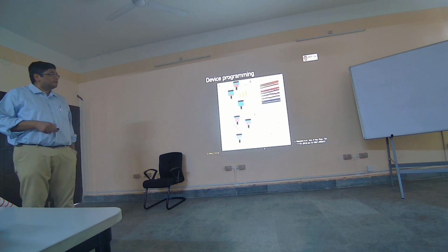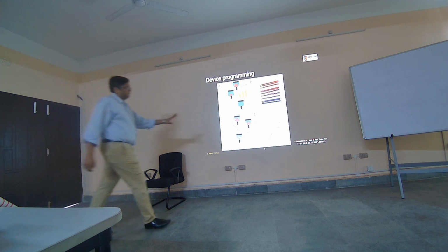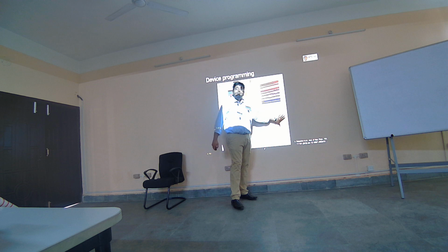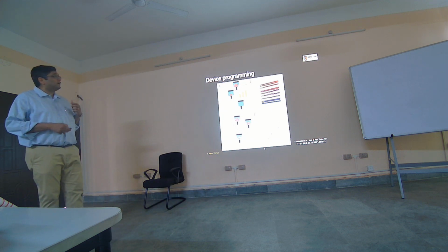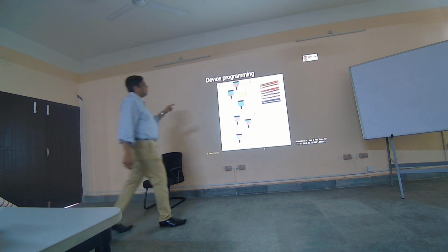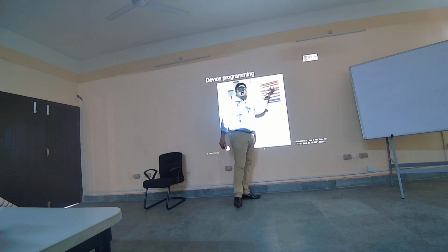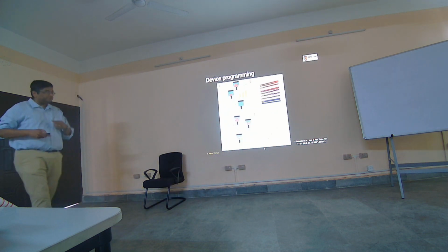What you see is that the conductance, if I plot a number of pulses, here is the problem. As we look at multiple devices, or the same device done multiple times, you see there's a variation. So when you're designing a circuit, you need to be aware of what this variation is and design for it. Another nice data is the various conductances as a function of time, which show not that bad relative to resistance. But again, as you go to high resistance, you see this drift. So that has to be accounted for when you are designing the circuit of this device.